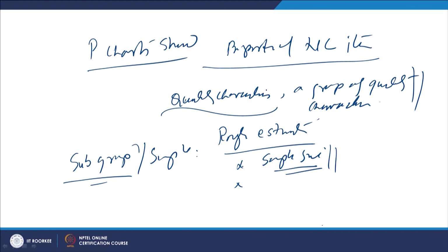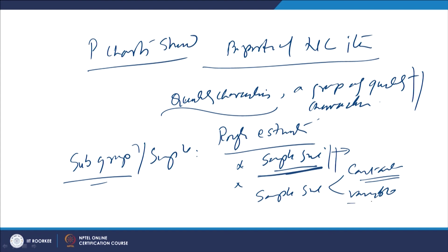Thereafter, it is always preferred that for the subgroup size, whatever we choose initially, a rough estimate regarding the sample size is made randomly, and samples of that size are selected from the lot. But there can be two possibilities. One is the sample size can be constant or it can be variable. So, in P chart preparation it is always preferred that the sample size is constant, but even if it is changing, then our approach will be different.